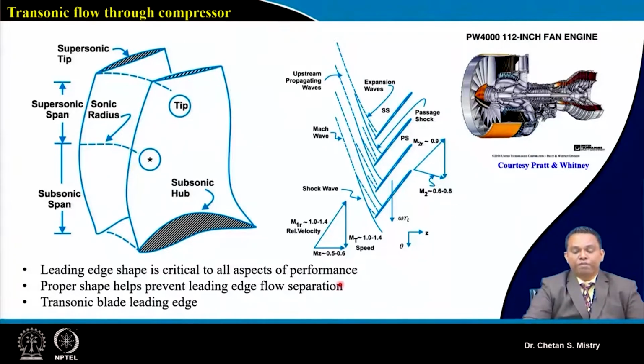So here, if you look at, this is representing in the sense of my Mach number. As we have discussed, suppose we are considering our fan that is facing the flow. We are looking for an entry Mach number in the range of 0.4 to 0.5. So it is in that range, and my relative Mach number is coming to be large.